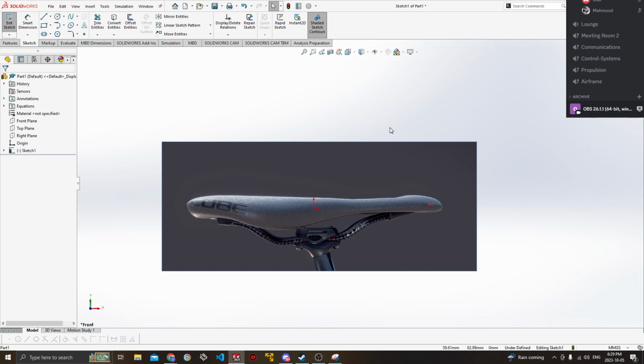And so what might happen is when we go to interface a part with a surface that we have created, if something doesn't line up in person and we remeasure that and realize that maybe our model isn't 100% accurate, if we try to go back into our model and make that one change, it's not going to propagate to the rest of the design, and it may require us to redesign the entire drawing. So what we want to do instead is make everything equation driven. That way, if we do need to make any changes, we can apply that across the entire model very, very easily.